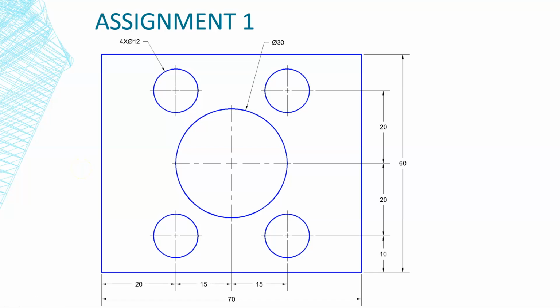So welcome back, and in this one it's just going to be straightforward and simple, like we did in another example similar to this one. We're going to figure out where we're going to start from. I'm going to start kind of at this direction here, and I'm going to wind up moving my UCS here. You can either move it there, or we can start off by just typing in 0, 0 and putting it at this location. For this one, I think it'll be a lot easier just to type in 0, 0. But remember that if you do decide to move that UCS, please remember to move it back.